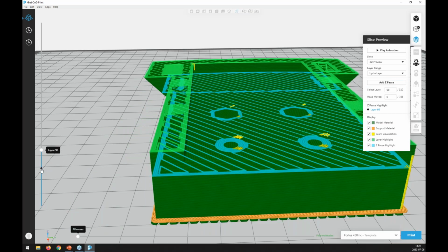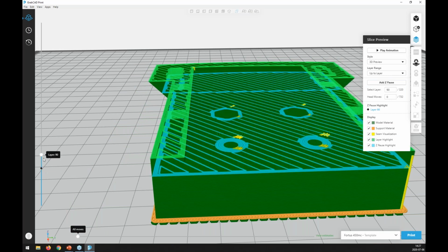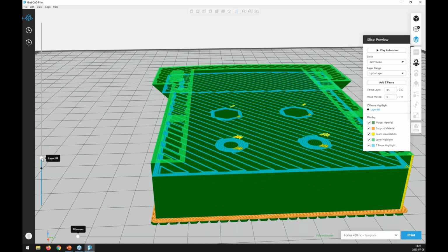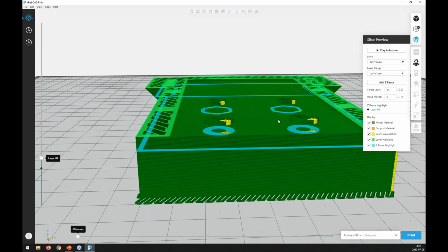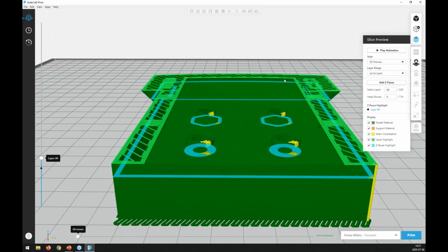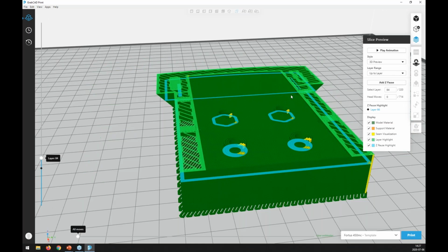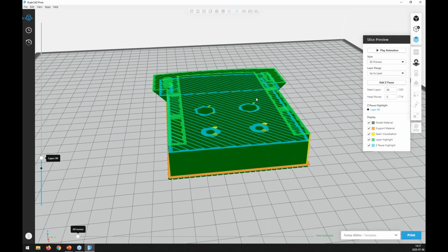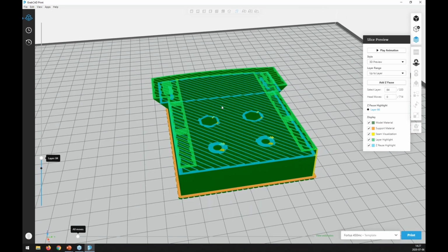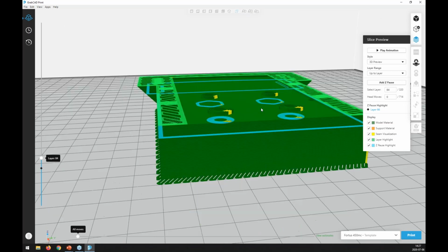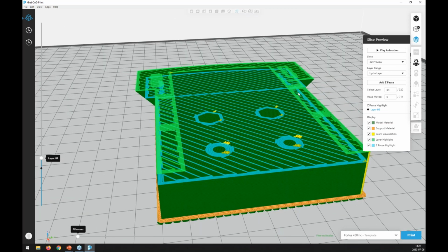And you can notice this from the left slider here, that this diamond shape shows you on which layer the pause was inserted. You also can have multiple. If you have multiple inserts in Z height, you can add multiple Z pauses, or even use it to change, for example, material to a different color, not a different material, but for example a different color if you use ABS or ASA. So that's it from my side from the GrabCAD Print